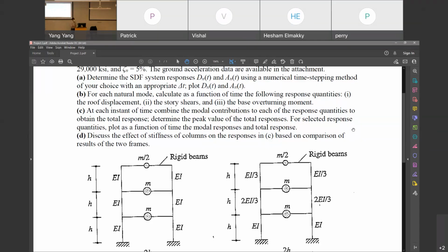You said the relative displacement times the shear stiffness. Yeah, as long as you have, after you are done with step 1, you should be able to tell the displacement for this level and this level and that level, right? If you know the displacement of each level, how can you tell the shear in this column?